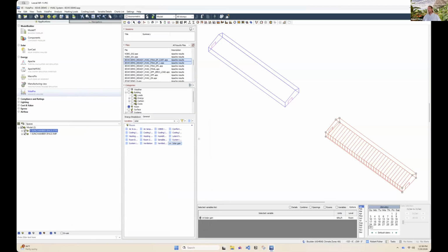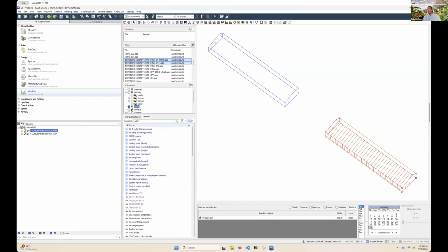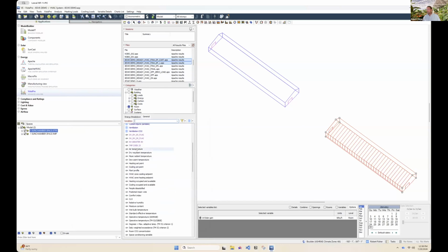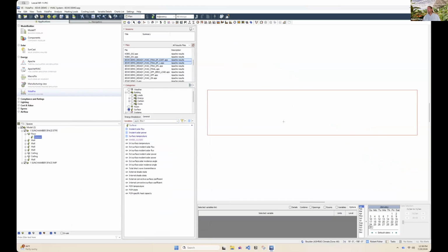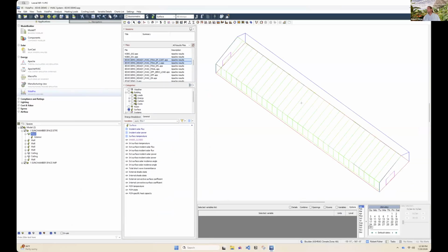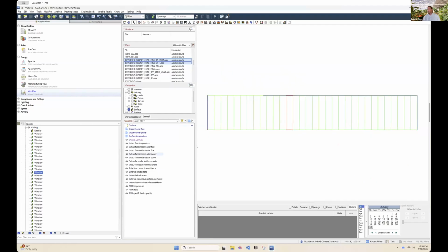Another thing we discussed or said we would discuss is the condensation on products. So you can actually go in here as well and just look at the room and not have solar. And then you can still go grab dew point and air temperature. So there's air temperature. And then we want the dew point temperature of a pane of glass. So we'll go in here, we'll grab one pane of glass, and I want to see the surface temperature of that glass.